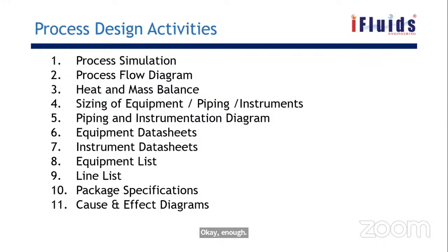So these things we are telling simply for the level, right? Similarly, in an exothermic reaction, my reaction temperature is 360. If I cross 360.5, it is very dangerous. It will lead to a runaway reaction.